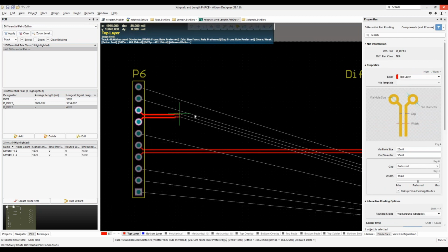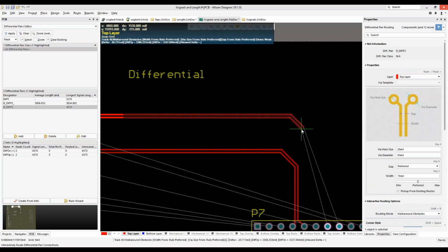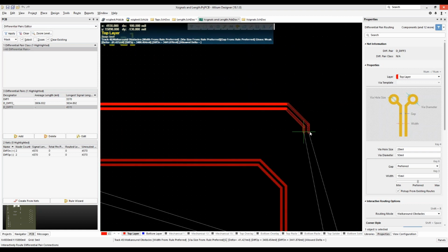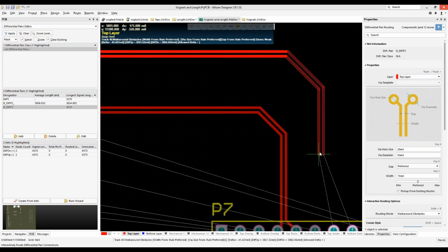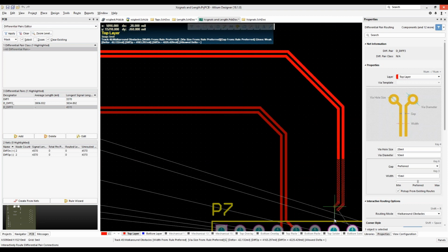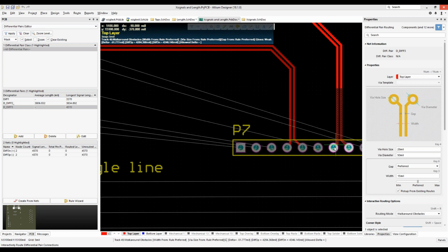So again, I'm going to click down to get these two together. Actually, backspace that. We'll bring this here. I'm also on a really tight snap grid, which is moving it around a little bit more than I want to. So before I start the angle here, I'll lock it down. I'll hit my Shift+Space bar. And one of the things I didn't mention is that with the space bar, you can toggle between end or begin. In this case, I am doing a start 45. If I hit my space bar, not holding down the Shift key, this is called end 45. So the space bar by itself will allow you to adjust that or toggle it in. And so I'll bring this over here as such. I'm going to click on it. And again, I'm going to bring this in, and boom, I'm done.